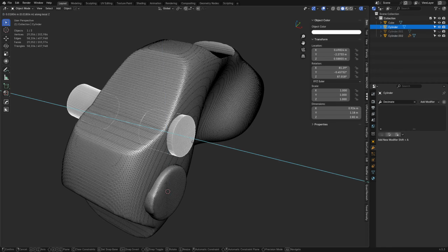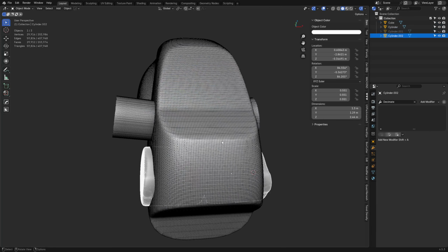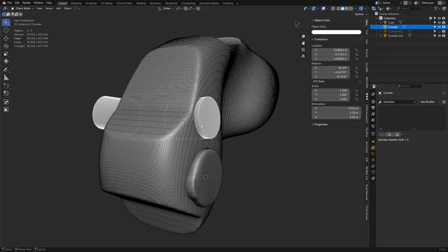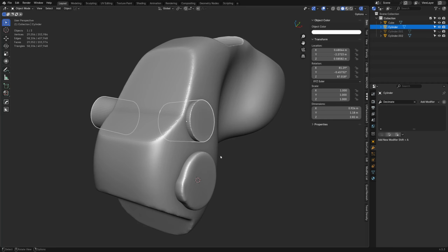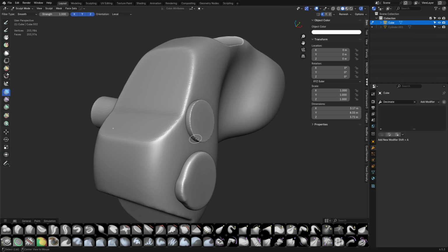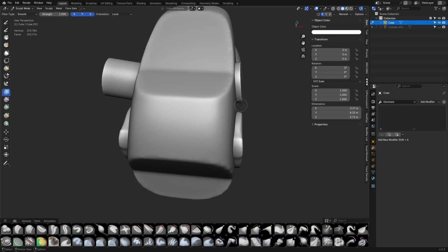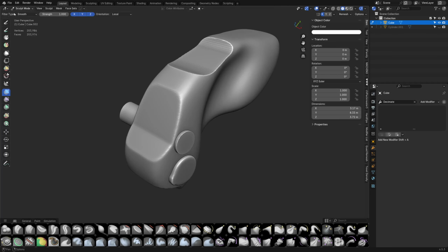And yeah, so we can move these in and out and not worry about destroying the whole mesh right off the bat. May not want to apply the mirror modifiers and stuff right away. That's fine. But if you wanted to do Boolean subtractions, you would do those. That's fine. But unions, you don't do that way. So how this works out is you take this mesh, this mesh, this mesh, you join them together, Ctrl J, go into sculpt mode. When you look at these, you can see they're inside of it, obviously. They're intersecting.